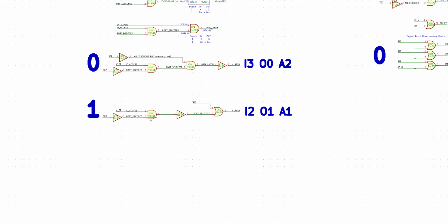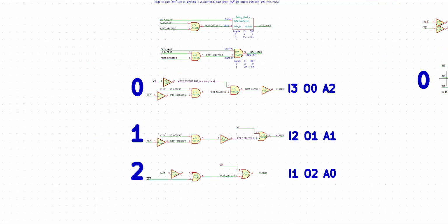Let me demorganize the other AND gate, so then I'll have all 3 versions. I'll have a version with 2 AND gates, 2 OR gates, and 1 of each. These are my 3 versions. For now, that looks like enough options. When I'm picking the final design, just like the other one, this circuit's pretty flexible since it can use any combination of leftovers: 2 ANDs, 1 of each, or 2 ORs. After I do the last piece of glue logic, if I need to, I can come back and add other variations of this equivalent circuit.